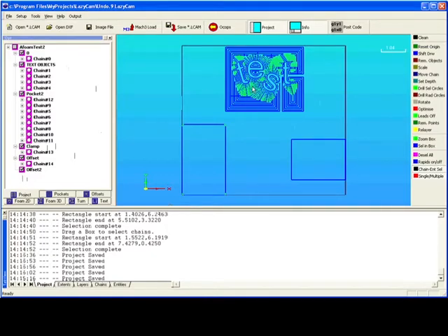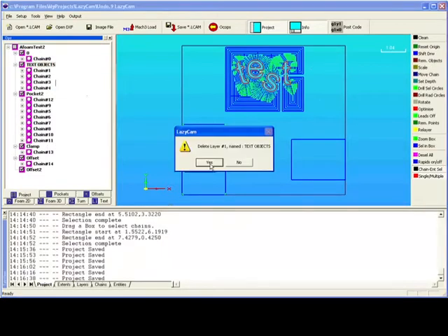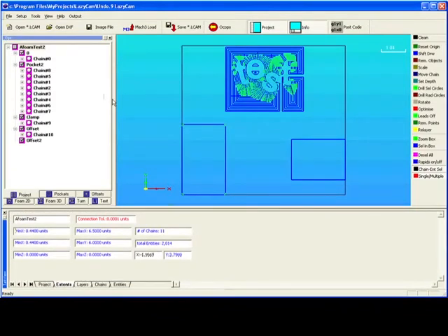One other thing that I should do in this particular job is delete the text entities, because we used those as islands. We really don't need them in the final job. Your choice, you can either click on the layer name and it will select them, and you can say remove objects, as we've been doing, or you can click on the layer, right click, and say delete layer, and it will go away.